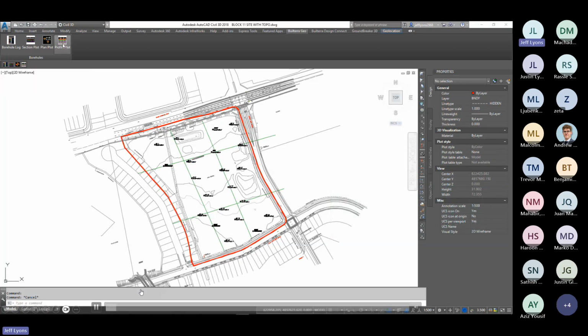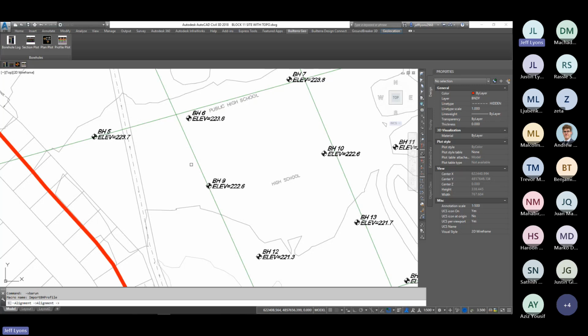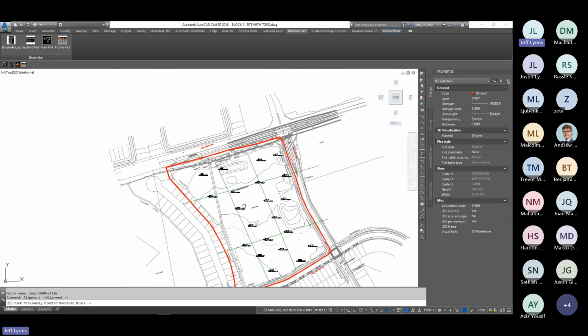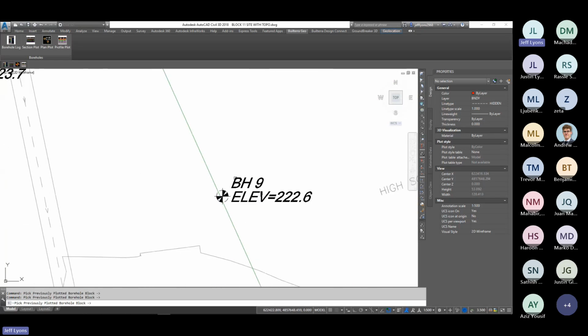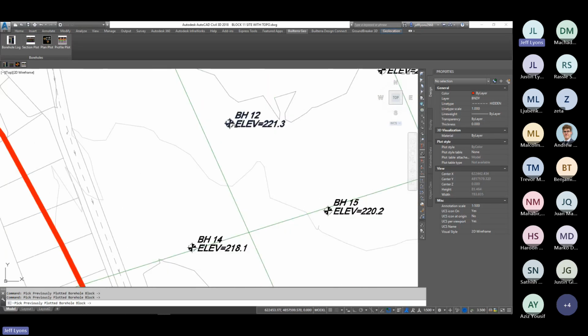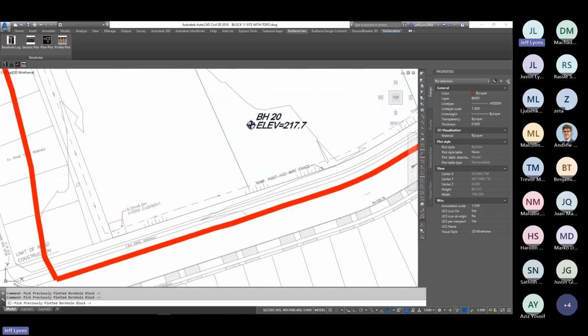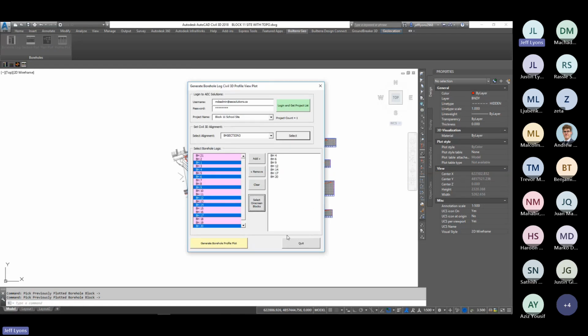And so when you pick profile plot here, you'll be able to literally project that to the profile view. So if you're using Civil 3D, alignments and profile views, that's it. You just grab the boreholes. It has an inspection ID attached to it, and you project the strata and values to the road alignment in this case. Okay, so we build out these extensions custom for companies based on their requirements.